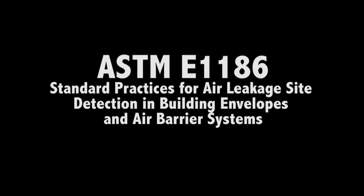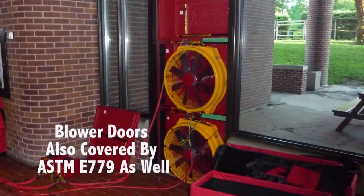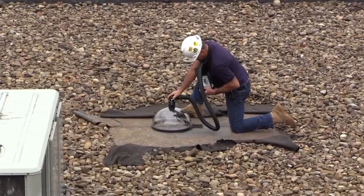ASTM E1186 is the industry standard for air testing. 5 methods are performed upon completion of the construction. 2 other methods are for localized testing of ties, for example. Again, the chamber is being placed over the tie, a pressure differential is created, and the leak is shown by virtue of the bubbling. The PosiTest is described in 4.2.7 of the standard, and it can also be used for forensics work, for example, on this roof after the fact, looking for leaks.